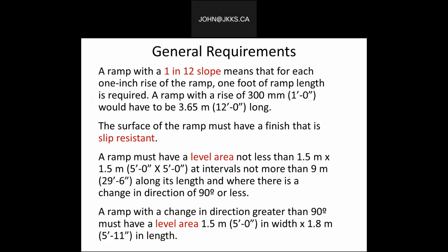A ramp with a change in direction greater than 90 degrees must have a level area of 5 feet in width, which is actually a little bit larger. We can see almost 6 feet in length.